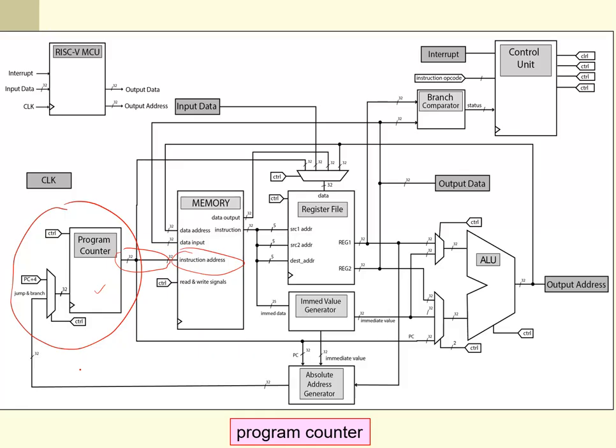The jumps and branches are the type of instruction that says, hey, go somewhere else to do something. And the idea here is it is under control. The control unit sends out a control signal to that mux. Also, it is a register, so typically I need to load that data into the program counter as well. So there's going to be a load control signal as well.